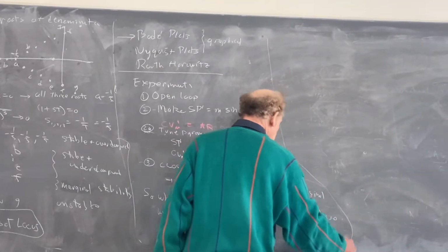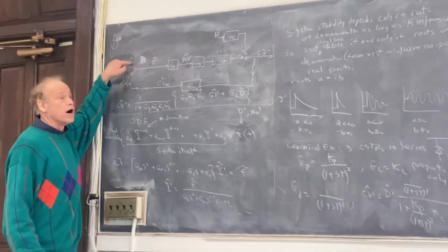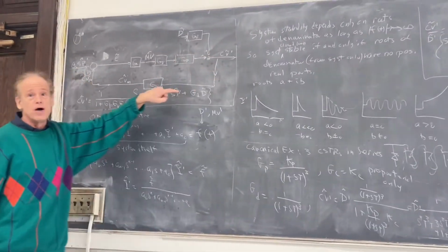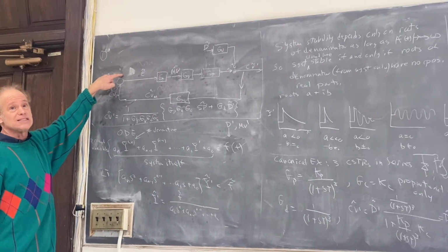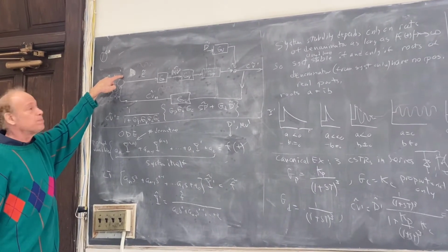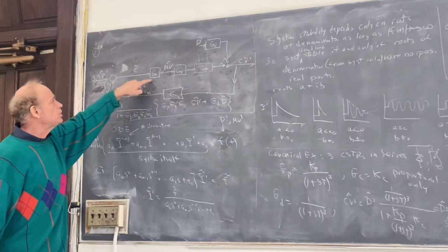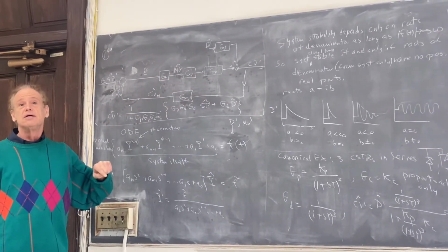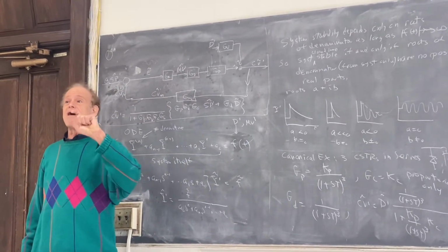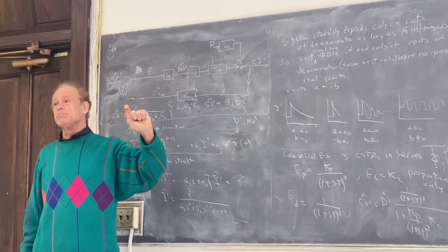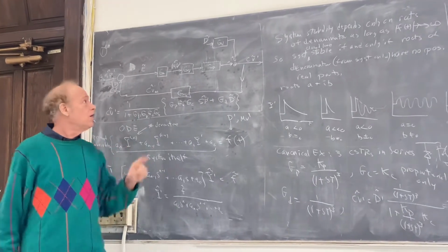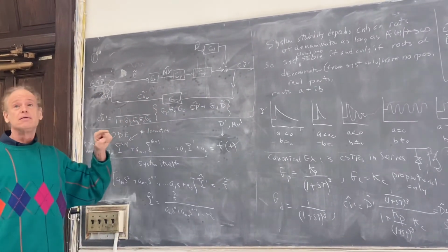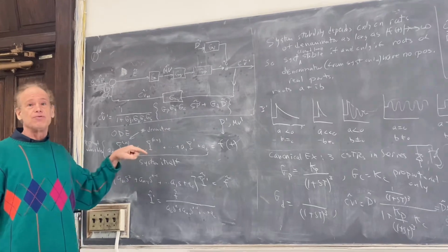So what does that tell me? That sine function started out as a sine of, let's say, magnitude 1. It goes through the loop once, and when it comes back here, it's still a sine function, but it's multiplied by the amplitude ratio of GC, GV, GP, GS. So now it has magnitude amplitude ratio times 1, the same sine function, just either bigger or smaller. When it goes through the loop again, it gets another factor of the amplitude ratio.